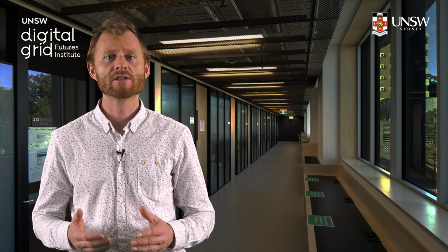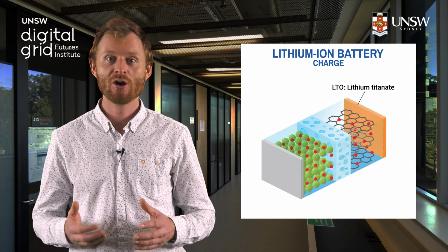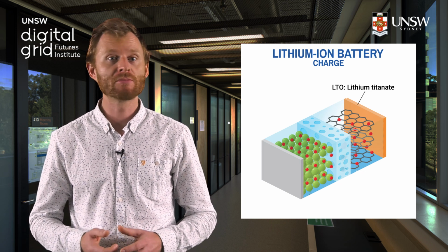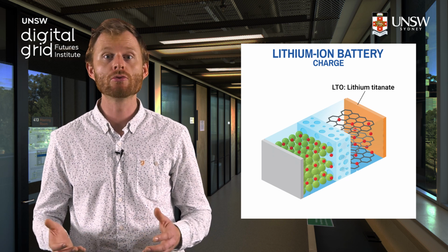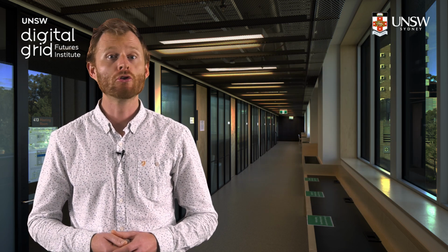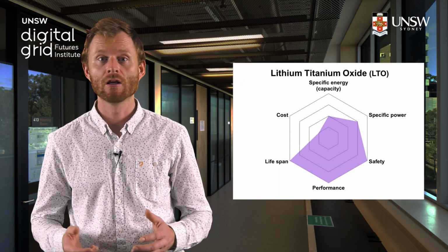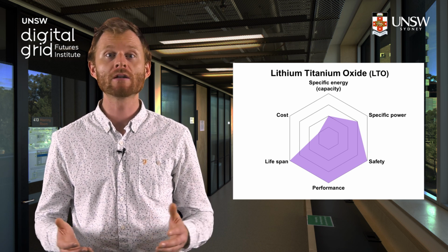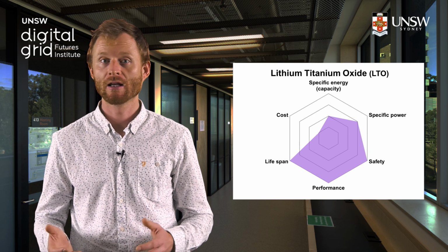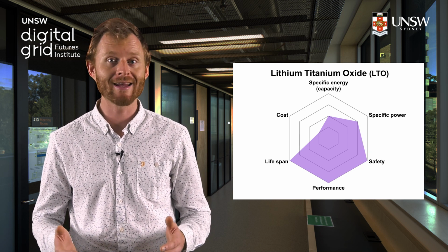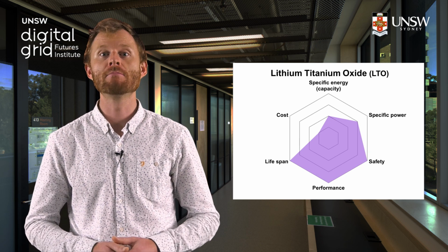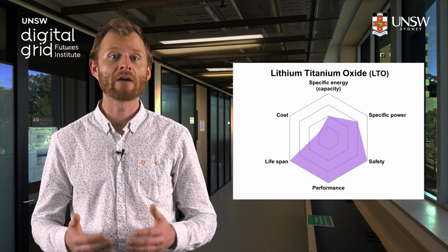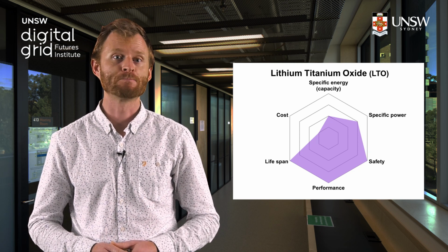As we mentioned before, some cells use a lithium titanate, or LTO for short, as the anode instead of graphite. NMC or LMO cathodes sometimes use LTO as the anode. Using LTO prioritizes safety with rapid charging capability and extended lifespan. This makes them great for medical devices, backup power supplies, electric vehicles, solar and wind energy storage, and aerospace and military applications. However, they are quite expensive to manufacture and have a lower relative energy density.